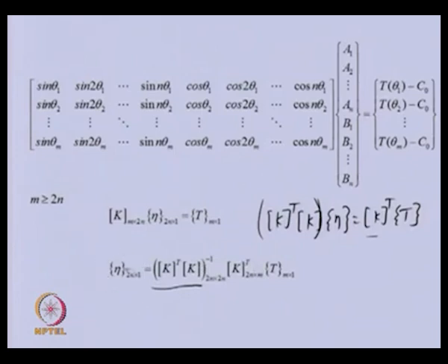You can see now we can get all these constants, which in fact represent what various sine and cosine harmonics are contributing to the t. The torque we have expressed in terms of sine and cosine and their higher harmonics. So, obviously, while designing, these frequencies and the natural frequency of the system should not coincide, otherwise we will have a torsional resonance condition.